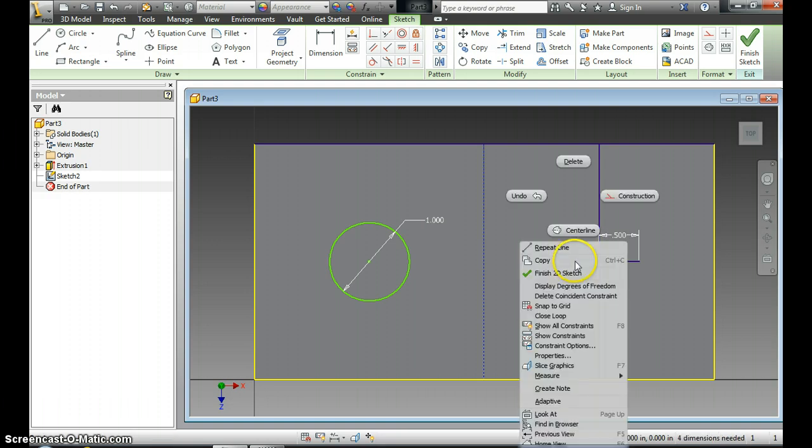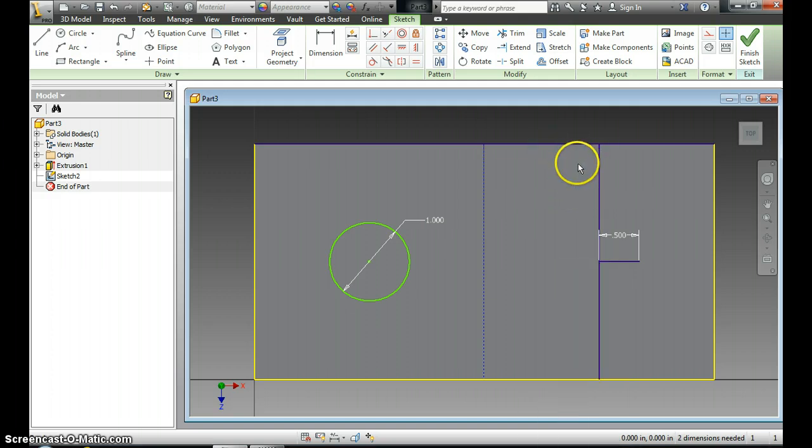Is that right? I'm not sure that's right, so I'm just going to delete it. I right clicked on it and I'm going to delete it and I'm going to make it again to make sure it's perfect. This is a precision measurement activity. So I'm going to hit 0.5 over here. Okay, that's better. And then I'm going to delete this line because I don't really need that anymore. And I am going to go 0.5 up. Just make sure your lines stay straight. And then I'm going to hit escape again. And I'm going to go 0.5 down.